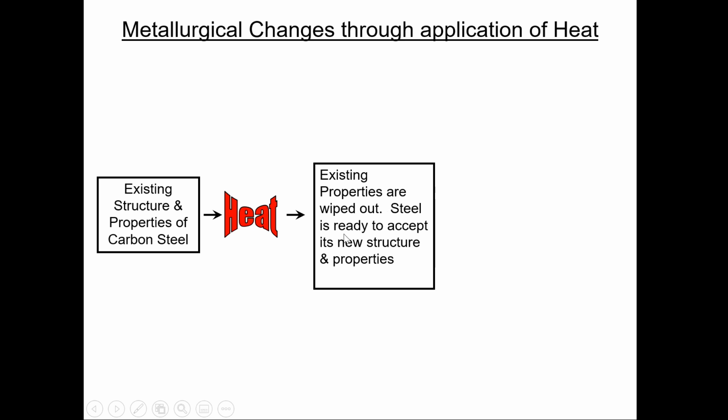When you get these materials to a certain temperature, even though you can just heat them up a little bit and weld them with a tool steel, if you get too carried away with your heat, they will lose their properties. They will no longer be hardened. If it's your intention to keep these hardened through your process so you don't have to requench anything, then you have to be careful how much heat you put into it because you will wipe those properties out.